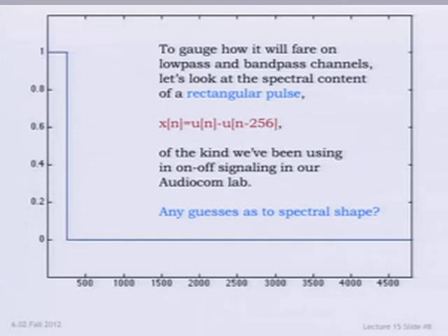At least one? Yeah. Low frequency is a good idea because for most of this signal, you've got essentially nothing happening, right? It's just flat. So you expect high spectral content at DC. But there is a sharp transition. So you might expect high frequencies associated with that. So do you think it might be low frequencies and then high frequencies, not much in between, or any thoughts? Okay, well, let's look at what it actually is.